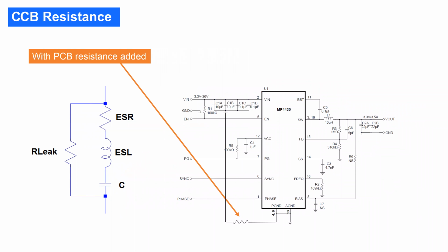What we usually don't take into account is that the PCB has resistance and even more inductance. That would be a lot harder to integrate in a simulation. But we should keep in mind that traces will have resistance and will have inductance.